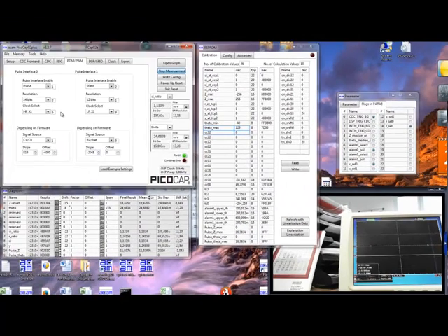Finally, I want to mention that you can select in this field here between PWM and PDM, and although in this screencast the output has been demonstrated on the basis of PWM, in most cases PDM is the recommended output option. Therefore, let's have a closer look at the two options again.